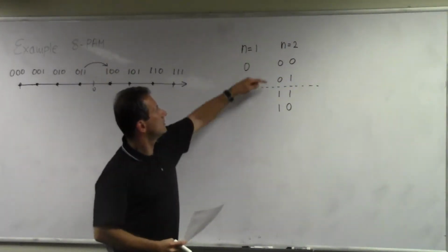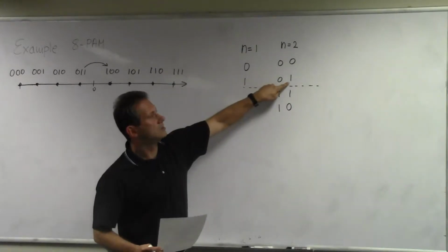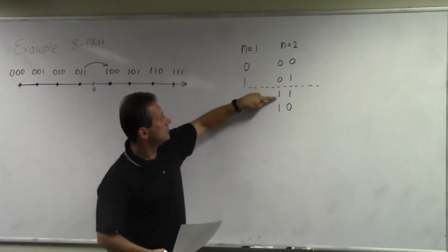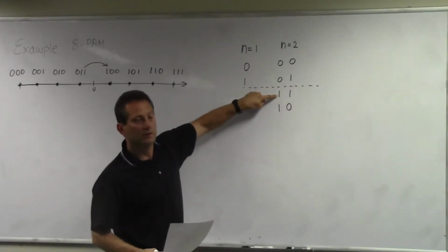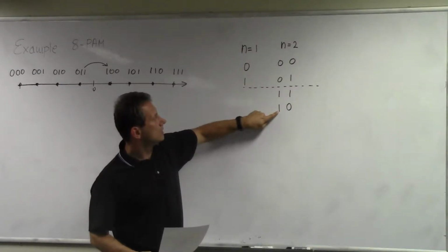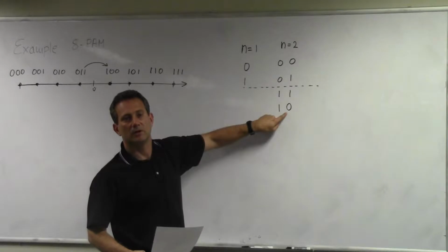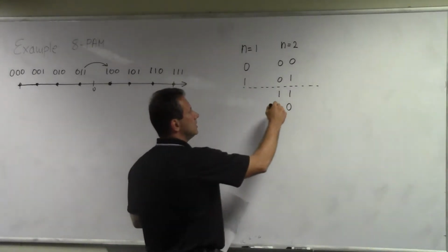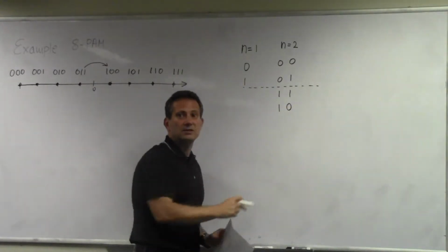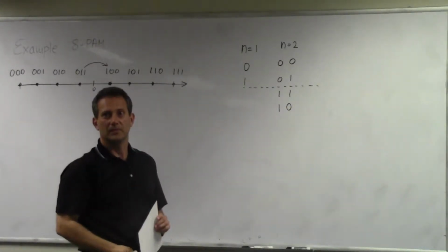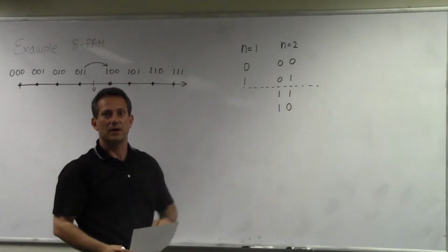So if you look at the difference between these two, it is 1 bit. Difference between these two is this 1 bit. Difference between these two is 1 bit as well. What you don't see here, but we'll show that this is of great use later, is the difference between these two, the first and last, is also 1 bit. Right? It kind of wraps itself around.